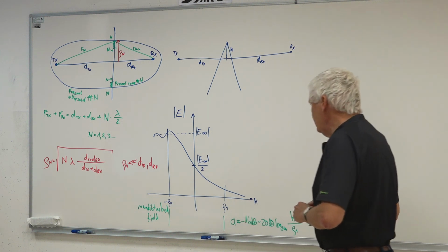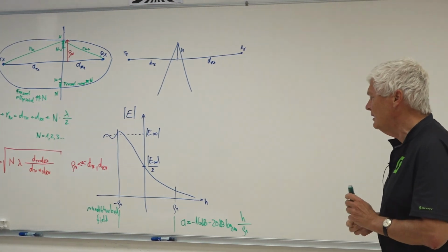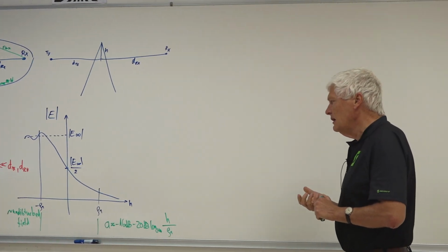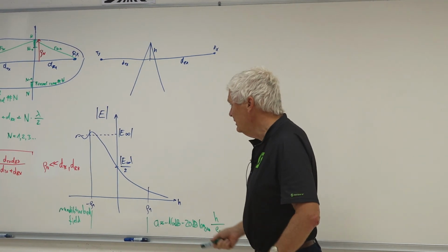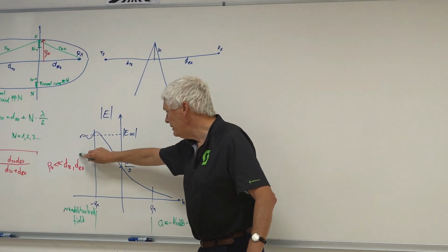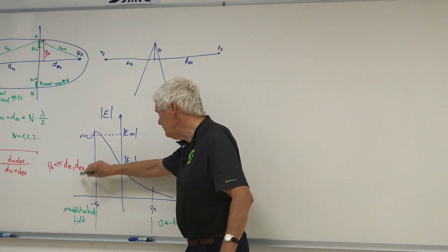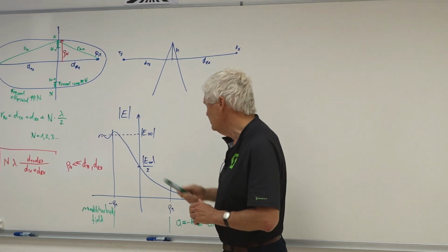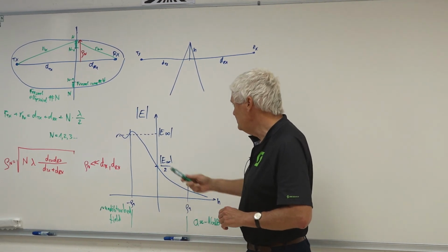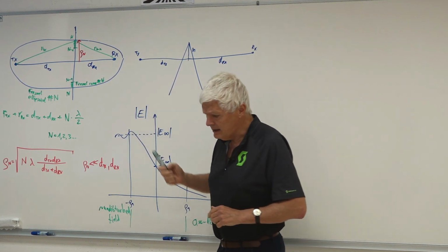So rho1, the first Fresnel ellipsoid, is for us really an important measure for the obstacle height. If the obstacle is below minus rho1, we have undisturbed field, almost undisturbed. There is some small oscillation around E infinity. This peak here is slightly over 1 dB.